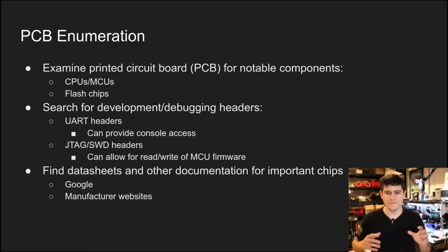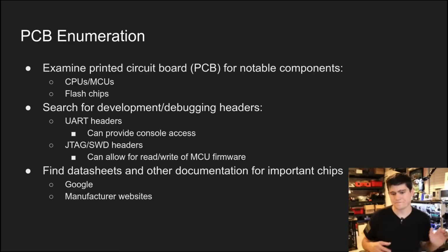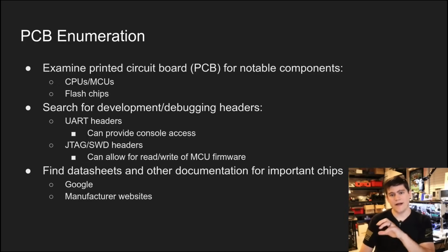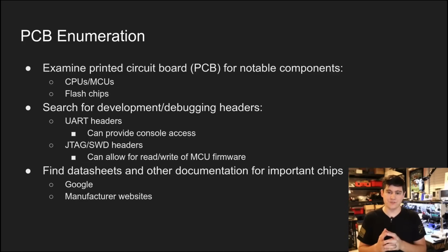Obviously, we've already foreshadowed that a little bit in our UniView camera here. We're also going to want to look for debug protocols like JTAG or SWD. This is going to be much more important, not that it doesn't have security applications if you're attacking a Linux device, but if we have a microcontroller target, oftentimes there is flash storage internally within the microcontroller.